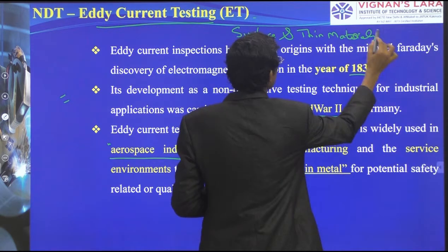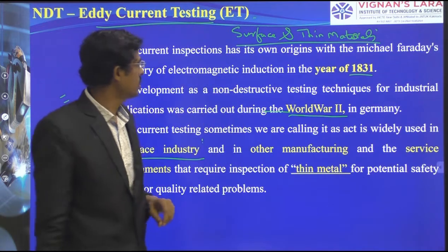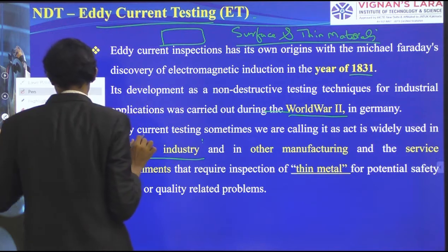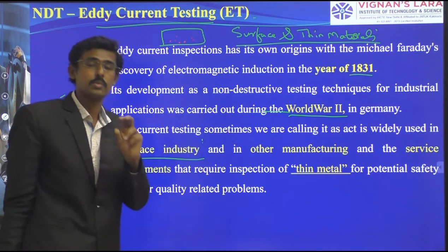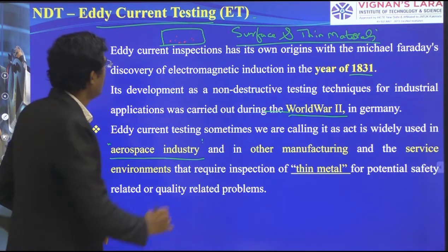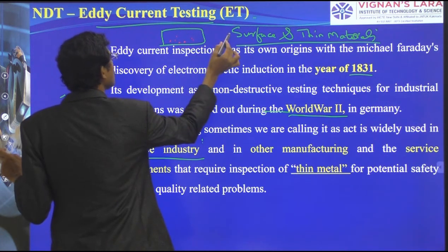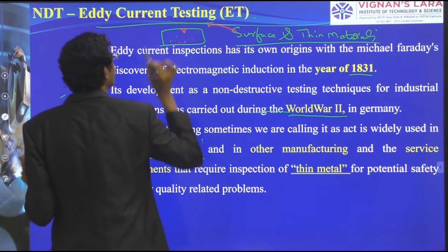In radiography methods, we did inspection for subsurface cracks or subsurface discontinuities. But here, with eddy current, we are going to concentrate on surface cracks, or cracks which are connected to the surface.